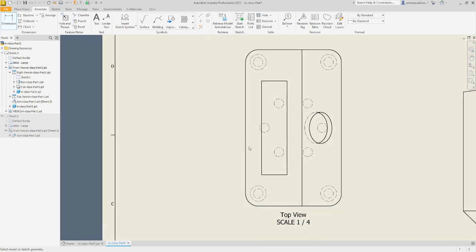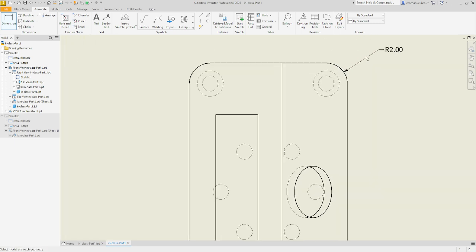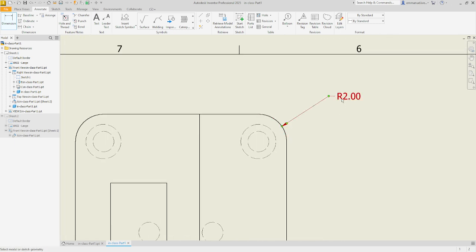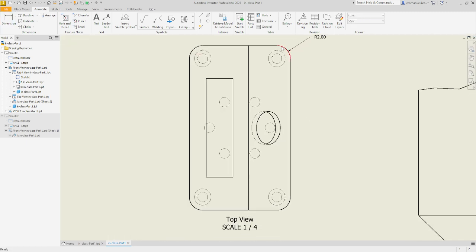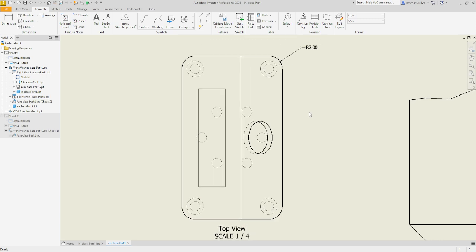And then for here, same thing. I'll just come in and add a dimension, and I'll say that this is going to be a radial dimension of 2 inches. Now, since there are technically 1, 2, 3, 4 radial edges, I don't have to put a dimension on each of them. I can just say, hey, there's 4 of these, or this applies in 4 places.